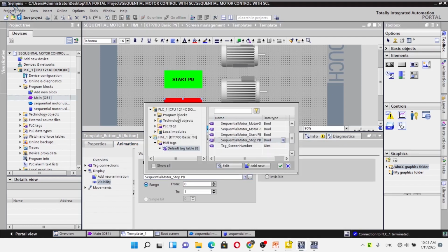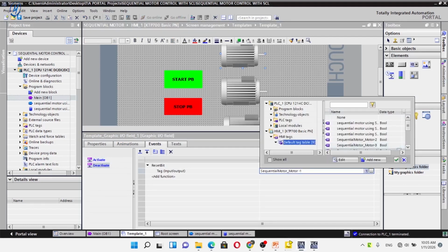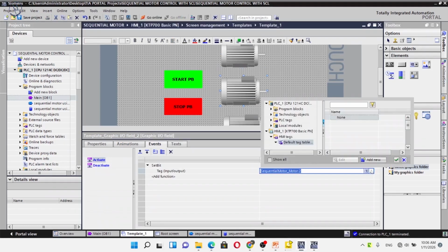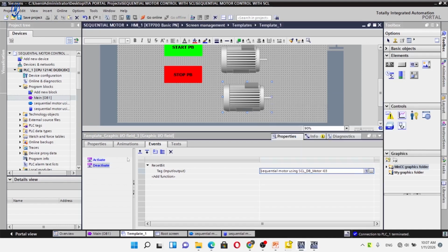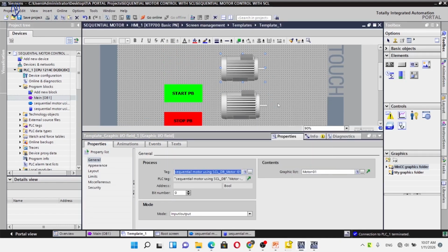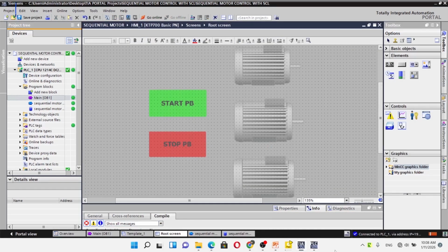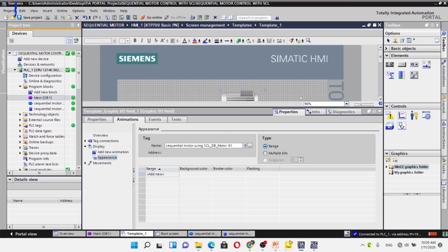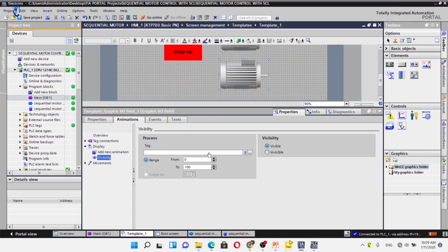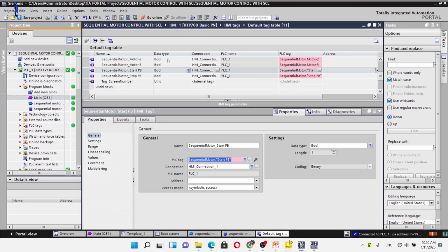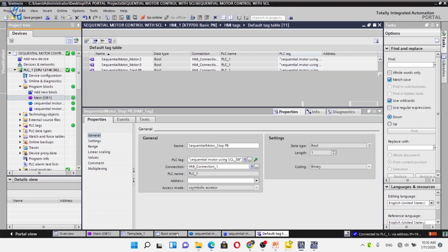Simulation, testing, and HMI visualization, compilation and download. The project is first compiled. The TIA Portal software checks for syntax errors, missing tags, or inconsistent data types. Upon successful compilation, the logic is downloaded to the simulation PLCSIM, or the physical hardware. This visualization bridges the gap between abstract ladder logic and tangible system behavior.